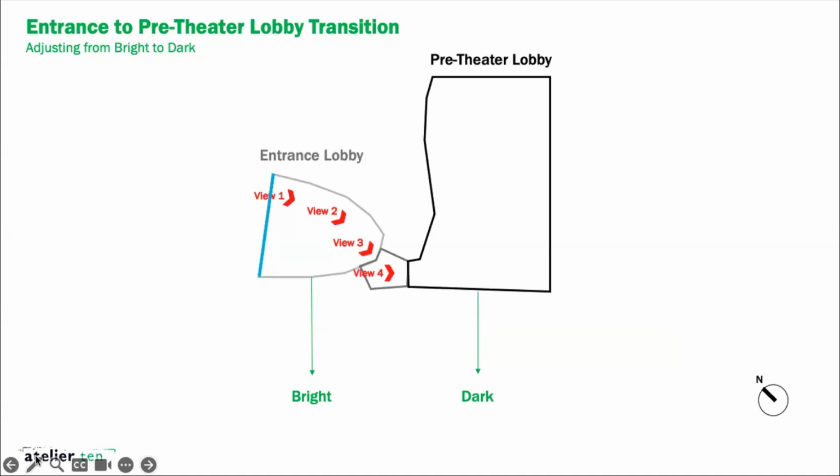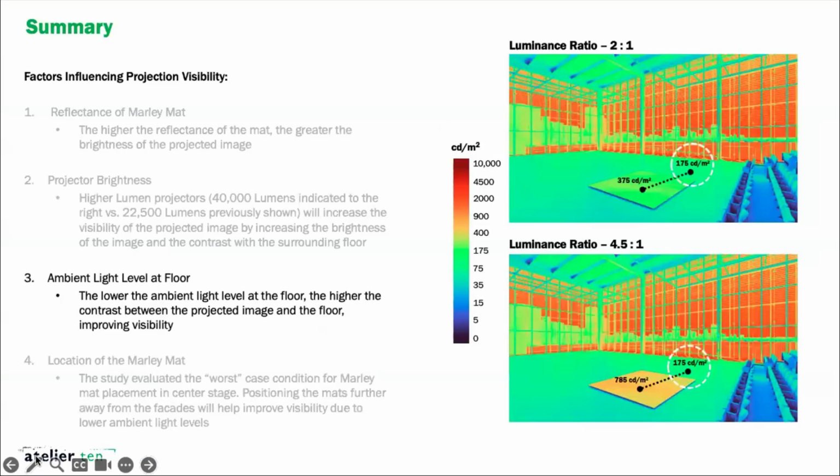Yes. Oh, no, sorry. For the DLI specifically, that's a very great point. This was before they even had any skylight design when we did that green wall, right? Something to consider is that you're going to have very different conditions when you have glazing, and the DLI is going to significantly reduce when you introduce the glazing. That's why I hinted at the idea that regardless of how open we keep that section, they're ultimately going to require artificial light. But it gives them a sense of where they can position the green wall to influence the artificial lighting design and minimize the amount of lighting they would need.